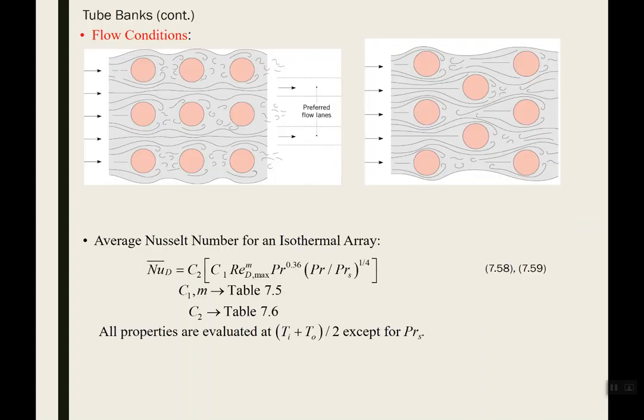You'd need to know what the heat transfer coefficient is on the outside so that you could figure out how well that heat exchanger is going to perform, and more specifically, so you know how big to make that heat exchanger, how much surface area you need, because the better the H, the higher the heat transfer coefficient, the smaller your heat exchanger has to be, which is going to come down to dollars at some point.